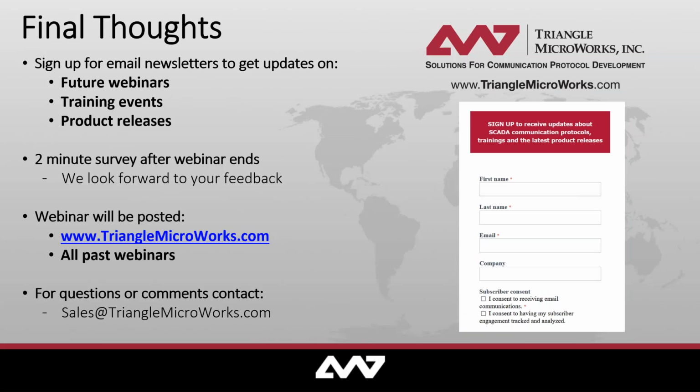Okay, thanks, Christoph. Next question for you. Is it best practice to use LGOS in the data set to the 61850 client so that you can see from the client if subscribers and publishers are getting what they need? It's definitely a good idea to include the information from the LGOS as an example in a report, so that you can have somewhere a tool, either a test tool like we have shown, Test Tree Pro, where we have our LGOS tool that summarizes the statuses.